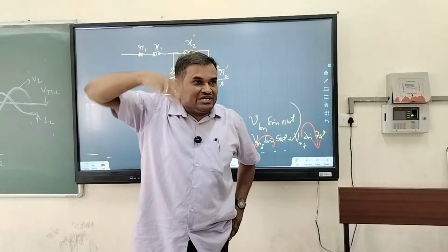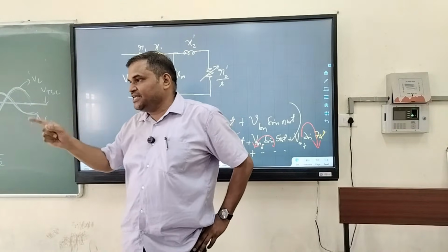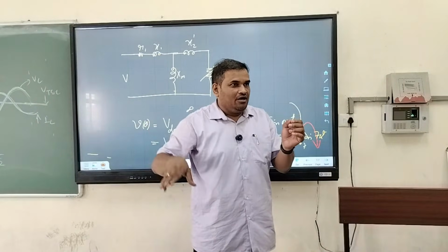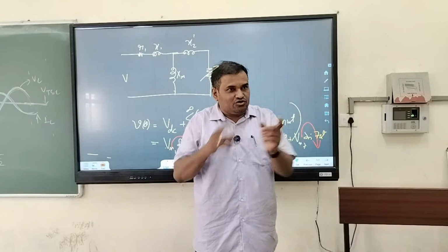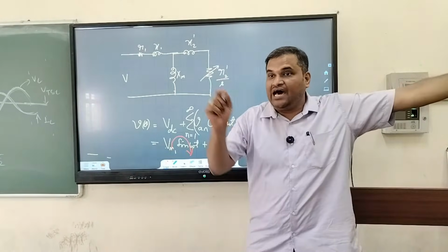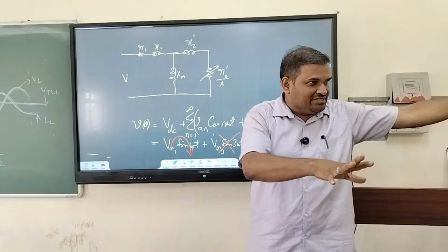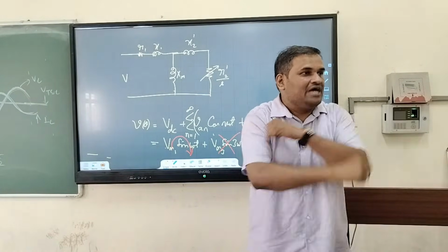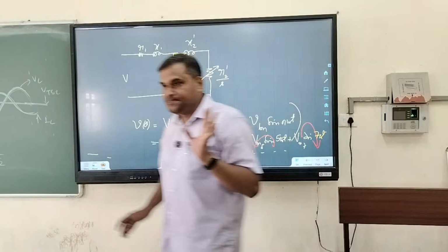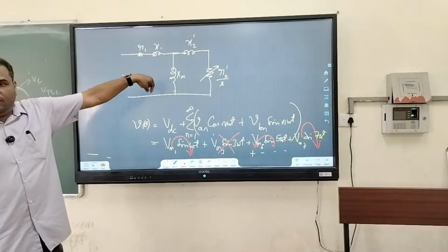So you have to take the signature of the motor's waveform, and by looking at the signature tell that if the input were sinusoidal, the signature would look like this, and if the fifth harmonic is present, the signature is like this. So by looking at the signature you can tell that somewhere in the supply a wire is loose, the supply voltage is not balanced, it is unbalanced, therefore the harmonics are created and you are getting this kind of problem. That is the job of an engineer in the plant. Now what is the effect on the equivalent circuit?